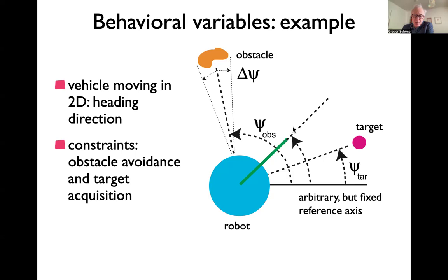They are directions in the world. The directions in the world are directions which you can move. It will be the directional aspect of the velocity of the robot, right? If the robot then moves forward along that direction, then you actually have the velocity vector. And therefore, when we're saying attraction to the target, we're talking about the attraction to that velocity heading direction that takes you to the target, or the repulsion from the obstacle. And that really means here from the direction that leads to the obstacle, from the velocity that would take you to the obstacle.